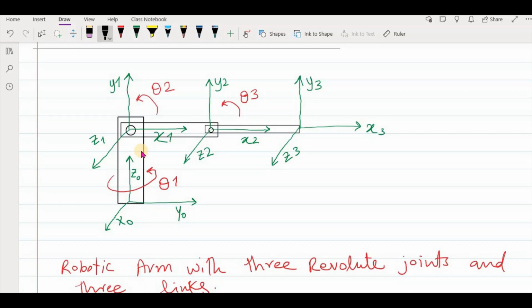So in this case, it's a revolute joint, and if you put z-axis perpendicular to this, it's coming out of this screen or this page towards you. So this z-axis is the direction of rotation of this joint. And then, as we also did in the previous slide, we always place x1 toward the length of the link. Okay, preferably we do that.